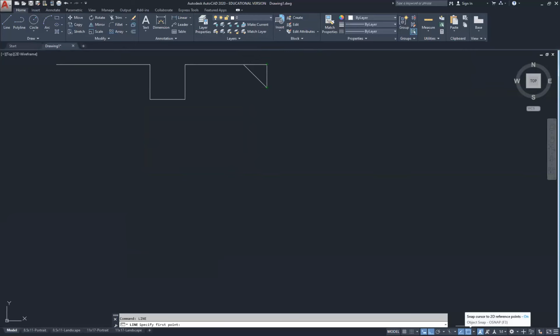When you have a situation like this, we could fix that by grabbing the dot here. When you select the object, we grab this dot and just place that in the middle. And that forces the dimension inside the bracket and then forces the arrows out, which is fine. What we want represented here. Once you're done with that, you can hit the escape key. It'll unselect the selected object. Let us continue with our dimensions.